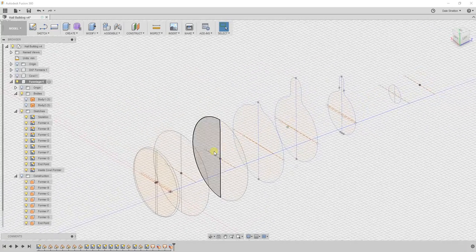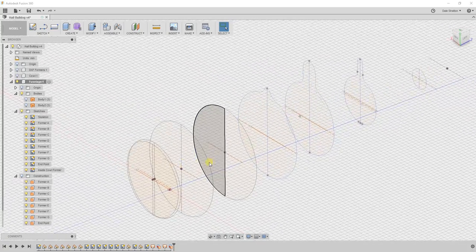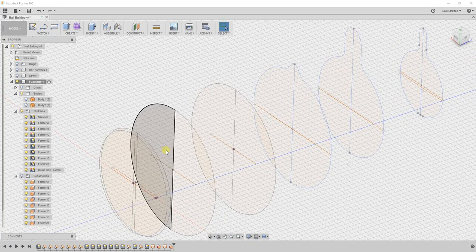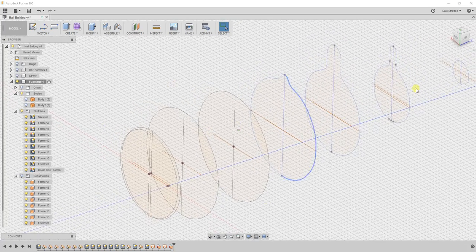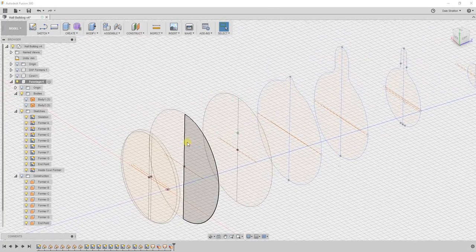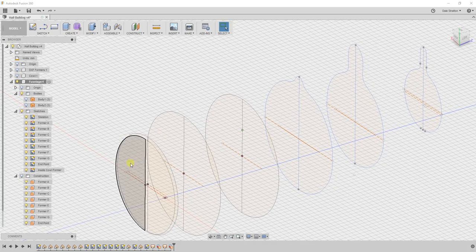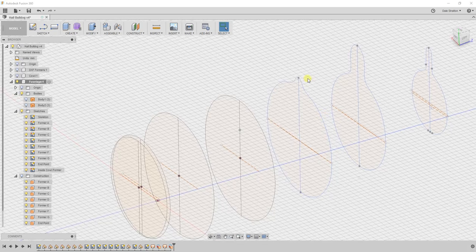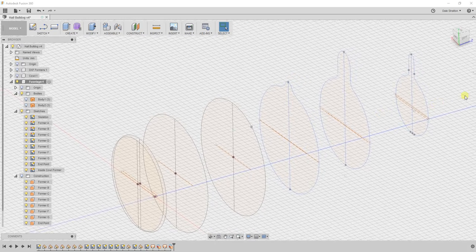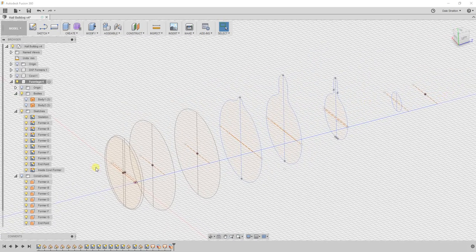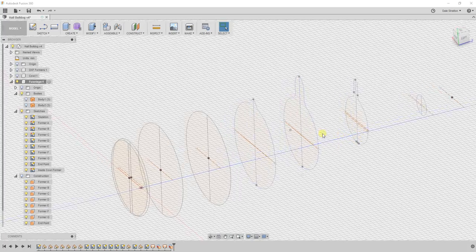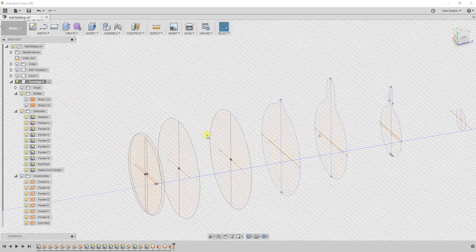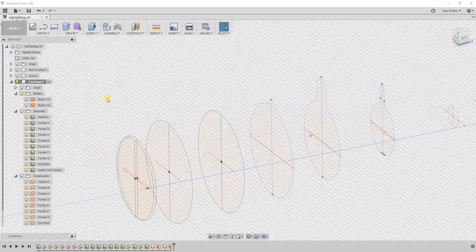One important thing to note, because we're going to use the Loft tool to make the 3D shape around this: I couldn't get the Loft tool to work with circular shapes. I had to cut them all in half and then do 2 separate lofts. Otherwise you get intersection warnings. And I don't know what that's about, so I just do it this way.